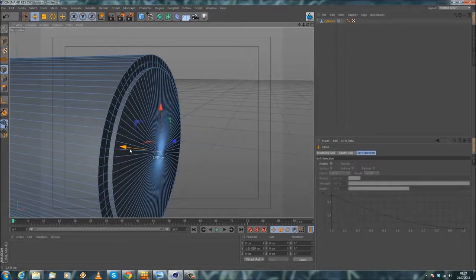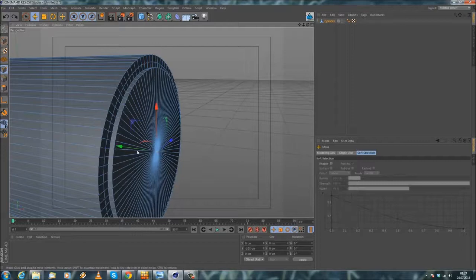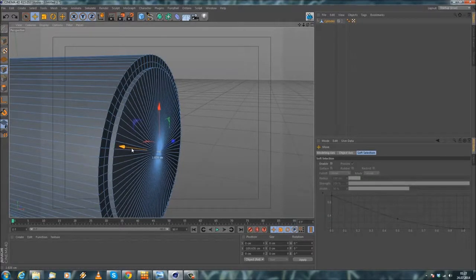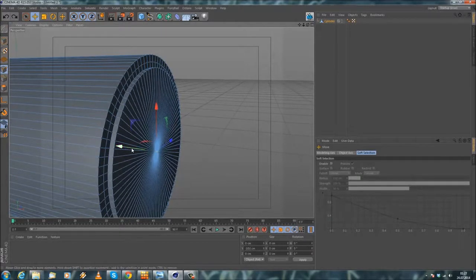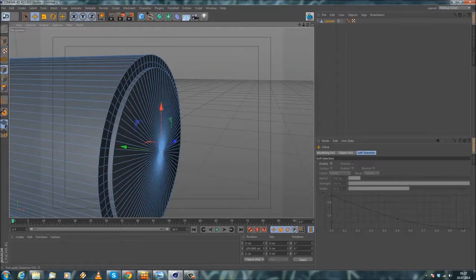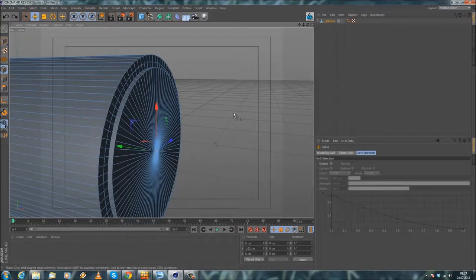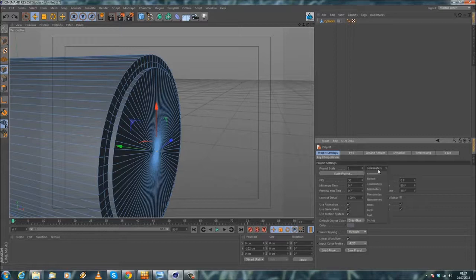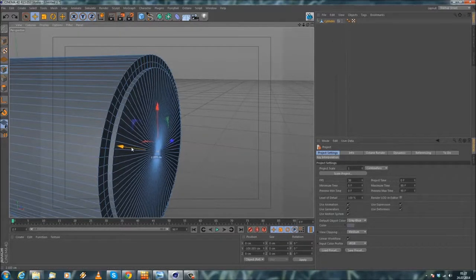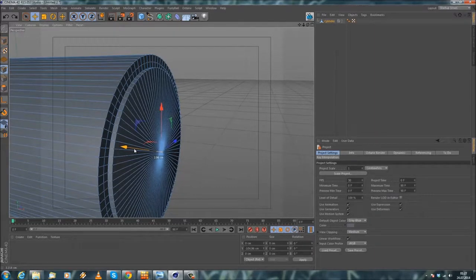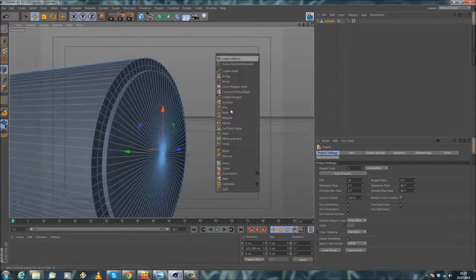As you can see here, you have this little thing that spawns with the centimeters. And if you don't have centimeters right now, you can just simply go Control D and then Project Scale, and then here go to centimeters. Okay. And so we'll just simply go here to 3 centimeters.